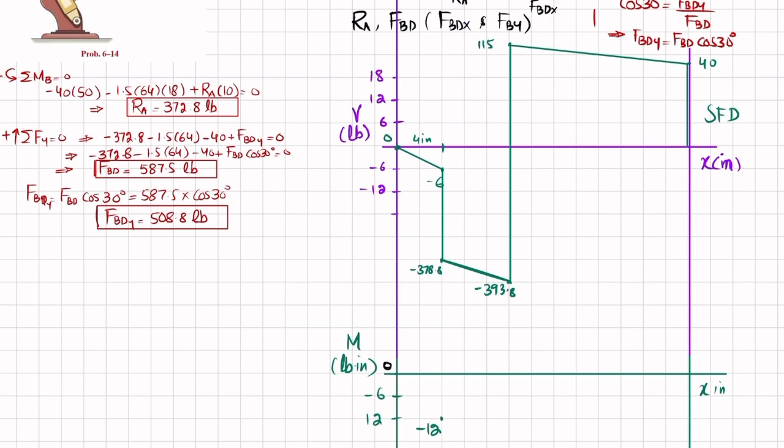Now you can see that this shear force is a 1 degree line and slope is decreasing. So bending moment will be a second degree curve and it will be in clockwise direction. So it will be like this. I will join these 2 points in a curve, clear, like this. Okay, this is the first area, and I will write it as A1.